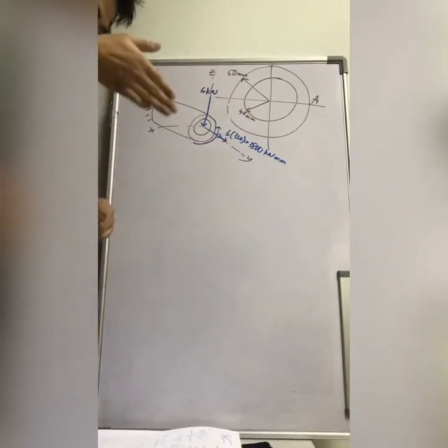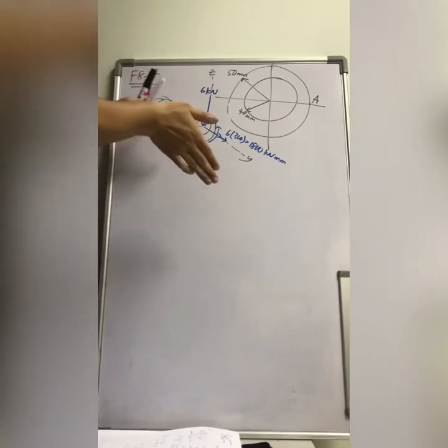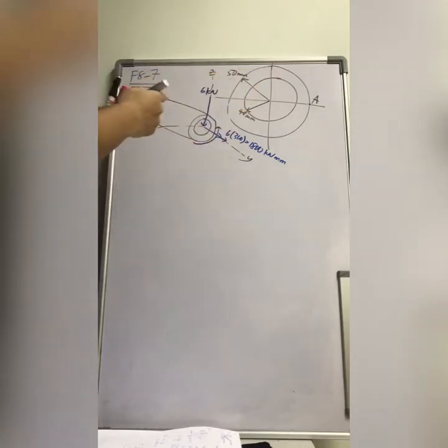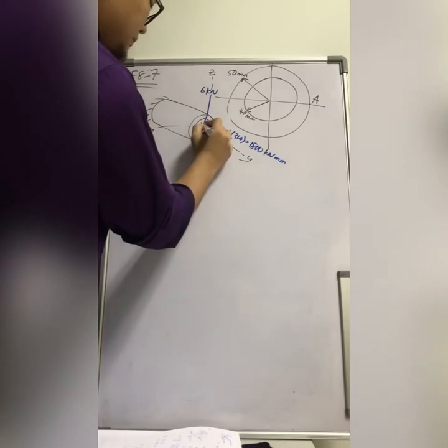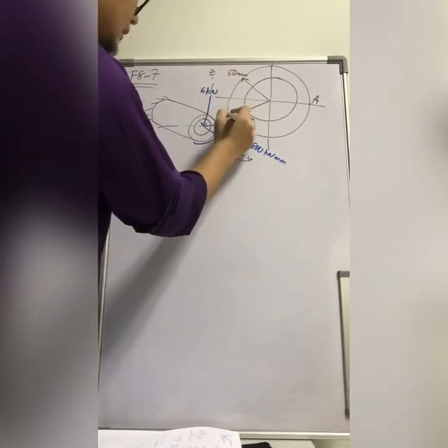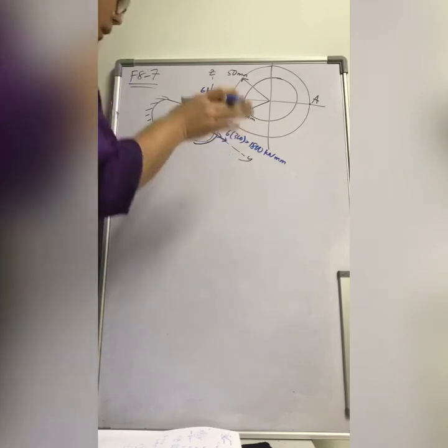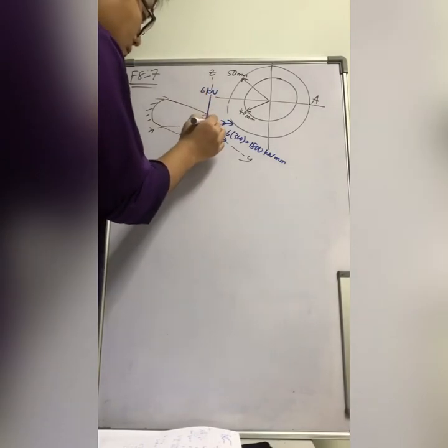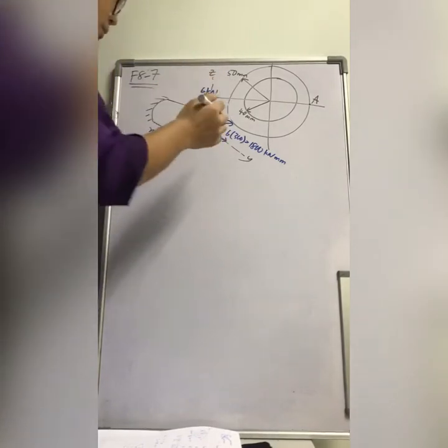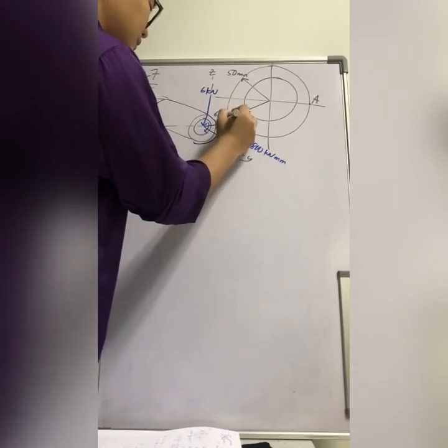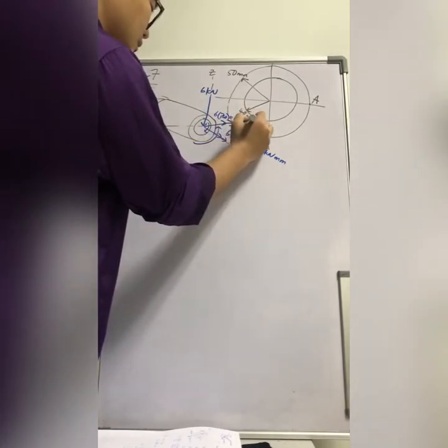And then what is this 6 kN, but now you take this distance, 300 millimeter, towards the section, and it will cause bending moment, isn't it? So you have bending moment, and this is 6 kN times 300, which is 1800 kN millimeter.